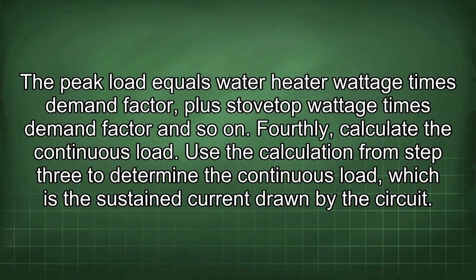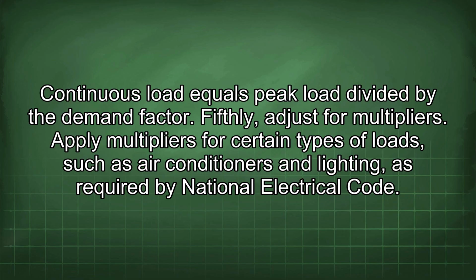Fourthly, calculate the continuous load. Use the calculation from step 3 to determine the continuous load, which is a sustained current drawn by the circuit. Continuous load equals peak load divided by the demand factor.